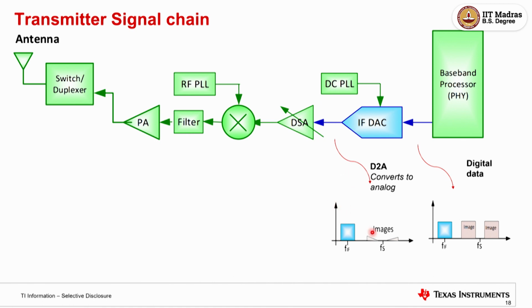So the process of doing that, right, the DAC, because it converts to analog, will try to filter some part of this image. So there is a filter. The way you look at it in the DAC, you run it at higher and higher frequency. We saw in one of the previous foils that there's a copy at Fs, and it will try to filter that copy. So if you see this image, there is something that is getting filtered. There is something coming up, but exactly at Fs, it will filter. That's what a DAC does.